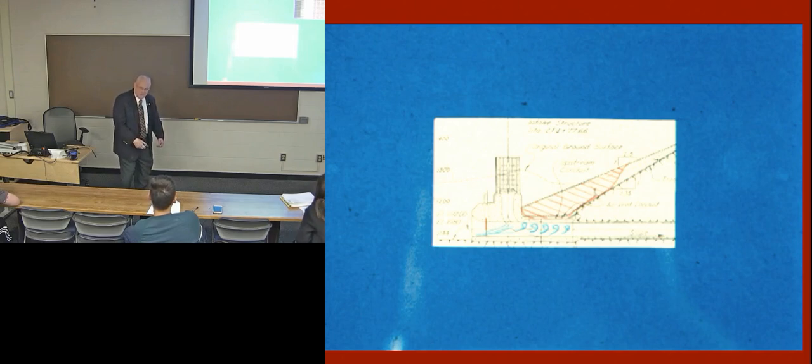They didn't have enough capacity to pull it up. The gate was stuck. And you've got maybe 200 feet of water above it. Well, that forced water under the gate. Turbulence occurred here. Turbulence destroyed the tunnel in this region, washed out part of the dam up here.